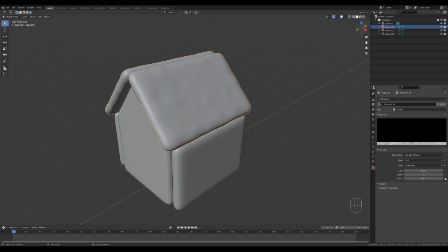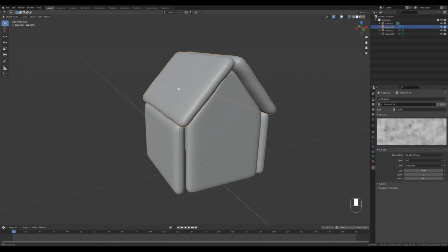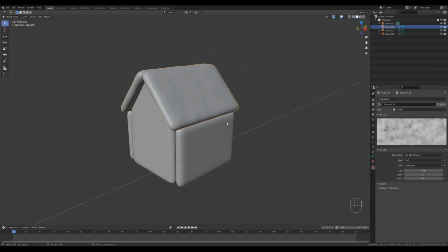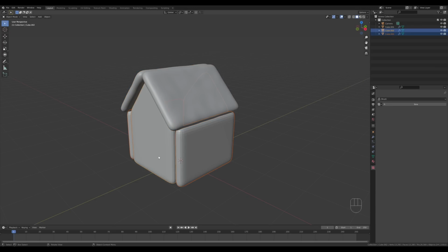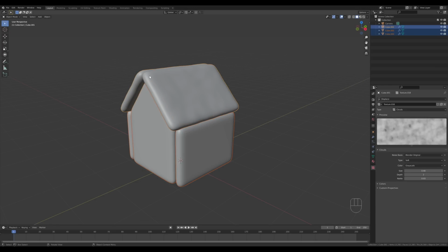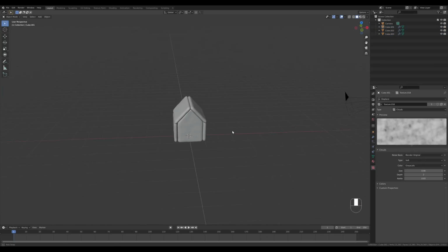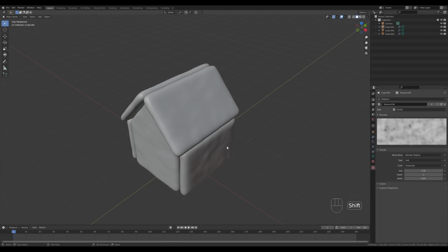And now if we go back to the texture settings, we can play with the size and make these bumps more dense or larger. I prefer to go a little bit larger here, something like this. So we have some organic shape in place. And now let's select these two objects down there by holding Shift, shade smooth, and shift click the roof. And let's press Ctrl L and copy modifiers. They will transfer the modifiers on those parts as well. So I think this is good enough to start with.